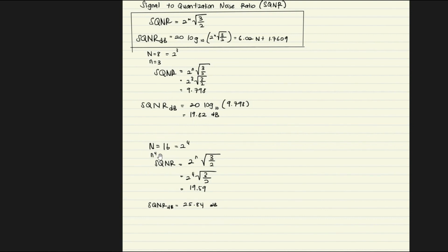Also the same for n equal to 16. We put the value into the SQNR formula and got the value 19.59, and then put the value into the formula, and again we got the final answer 25.84 dB.